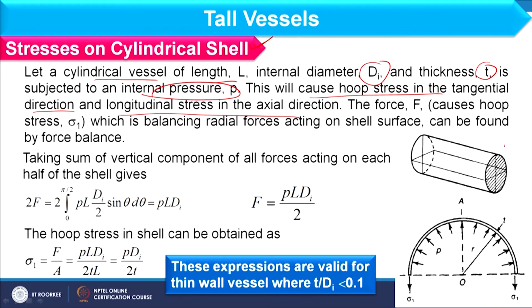So, if I have this vessel which is cylindrical in shape and this section is covered. Okay. So, if I have pressure inside this, what will happen? This pressure will be acting in this way, okay, at the periphery. It means it will try to expand the periphery from inside, fine. So, in that case it will generate the tangential stress, which we also call circumferential stress or hoop stress, right.